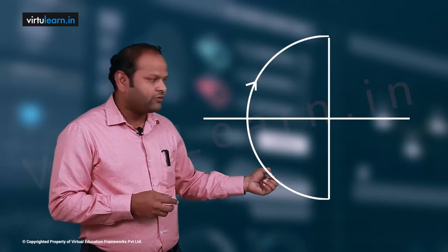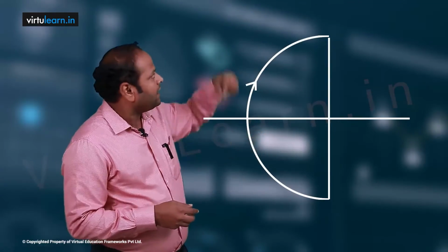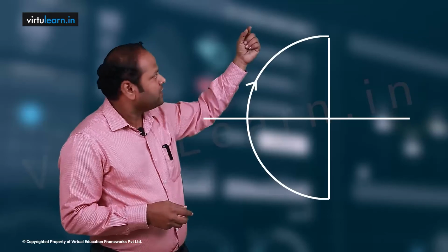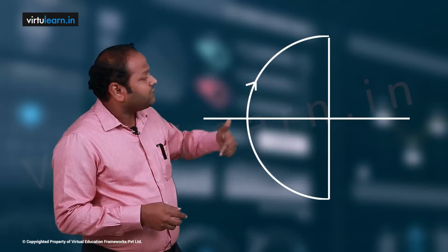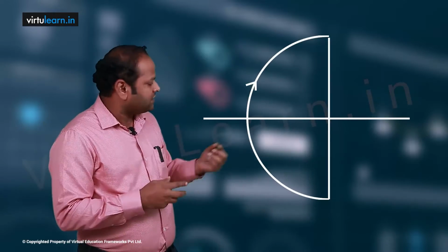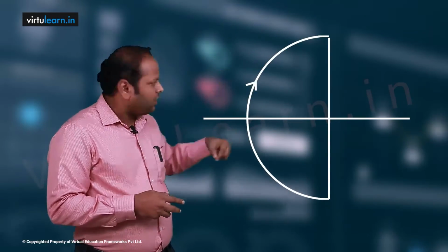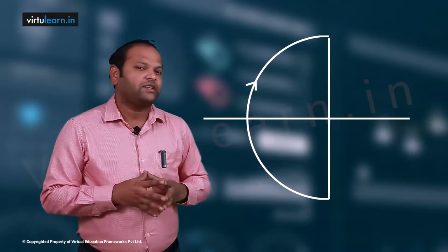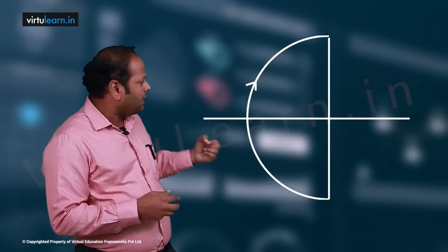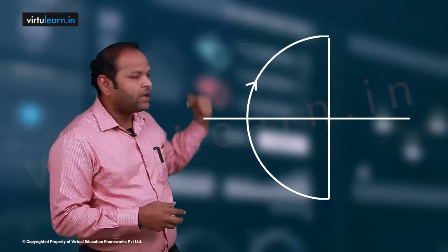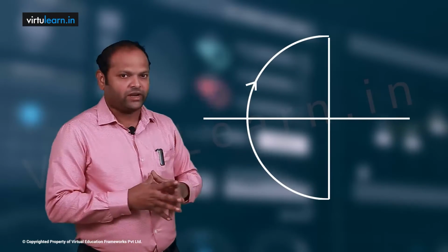The starting point of the polar plot is minus 270 degrees. So starting is here and ending is here of the path 4. When you take these 2 points, which direction should we take? There are 2 directions. I can go like this and I can go like this. But the path 4 direction, we know that it is always a clockwise direction. So clockwise direction means start here and go like this. So this is my path 4, which is from minus 90 to minus 270.